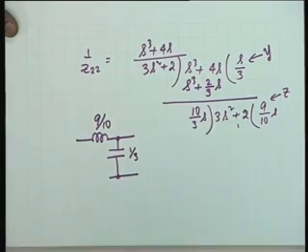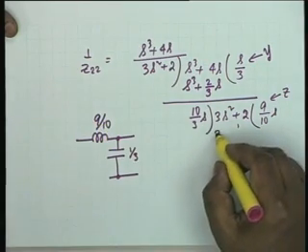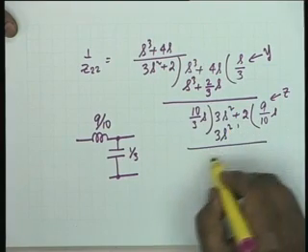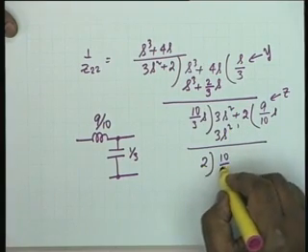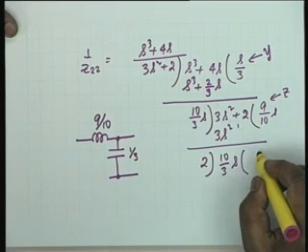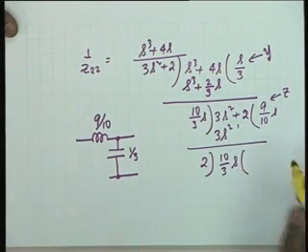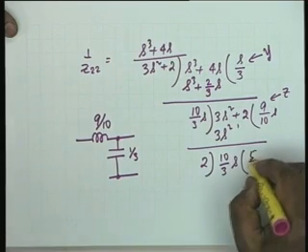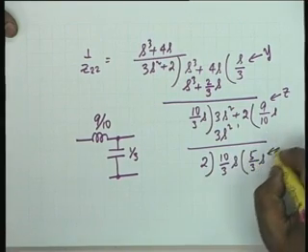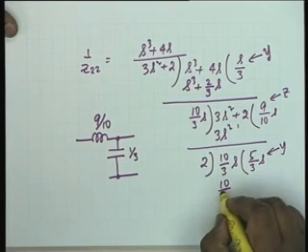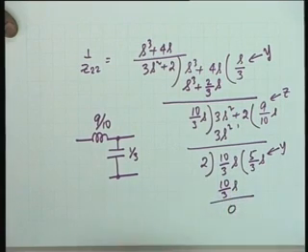Let us go ahead and draw it. 9 by 10S, this gives me 3S squared. I am left with 2 divided by 10 by 3S. So, I have 6 by 10, I am sorry, 5 by 3, that is correct, 5 by 3S, and this is an admittance. So, 10 by 3S divided by this gives admittance 0, which corresponds to open circuit.